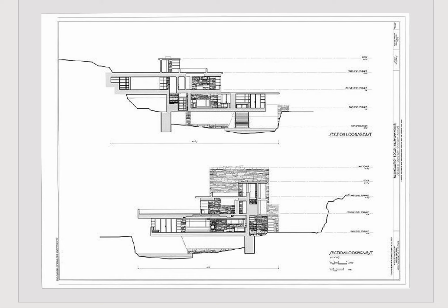Experiment. That drawing that I just showed you from Frank Lloyd Wright here has been turned into CAD. Someone put it into Revit or AutoCAD, or I'm not sure what software. I can't zoom in to see. But you can see that's exactly what happened, right? The darker lines are the ones that have been cut through. The secondary lines are the outlines around the house and the openings through the windows. The third set of lines are the features. The fourth set of lines, we haven't talked about this, it was called poche or pattern. And then the fifth set of lines, in terms of darkness, are the dimensions.